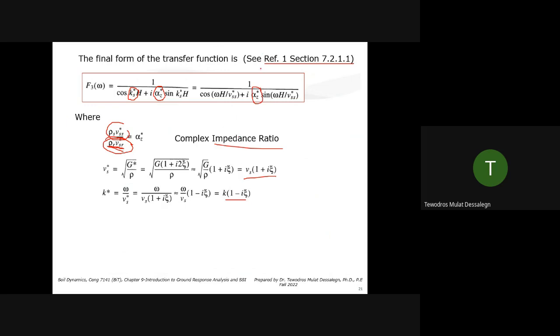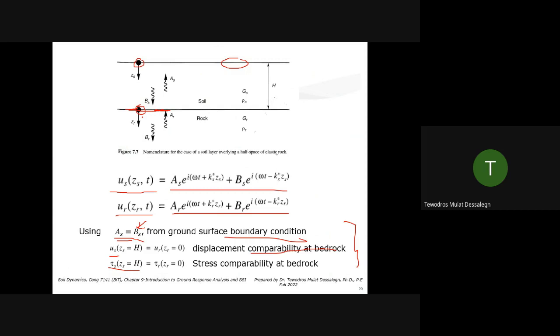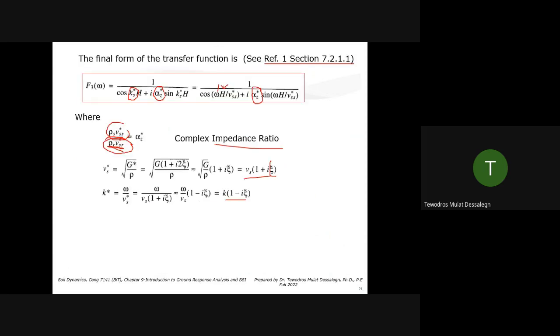But this is the form of the equation. This equation remains the same as far as you have it for any soil. H may vary for different soil, input may vary, Vs may vary, but the equation remains the same. So we introduce elastic rock now. Rock with some damping. We introduced damping in the soil. Yeah, we have damping in both cases, even if I didn't show it here. That damping value is right here.